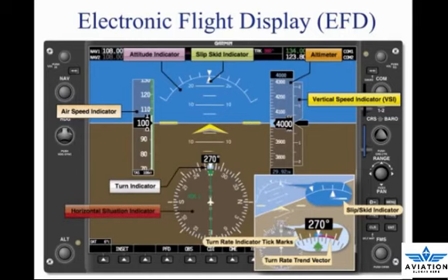The multi-panel digital flight displays combine all flight instruments onto a single screen, which is called a primary flight display, or PFD. The traditional 6-pack of instruments is now displayed on one liquid crystal display, LCD screen. Configured similarly to traditional panel layouts, the ASI is located on the left side of the screen and is displayed as a vertical speed tape.